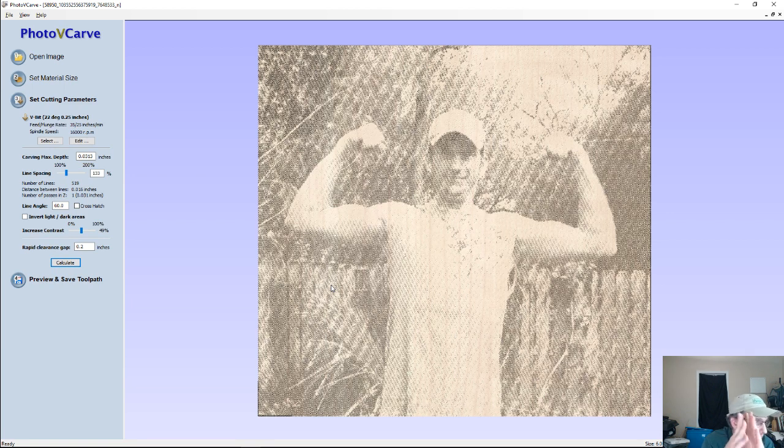If I need that nice little flat bottom cut in a particular design, instead of the V-bit having to do all the work when I choose to use a flat bottom in my V-Carve toolpath, I just do a regular V-Carve, and it already has that flat tip on it, so it kind of creates that flat bottom for me. And if there is any cleanup, usually there's not, because of my step over and everything, but that's what I would use that for.